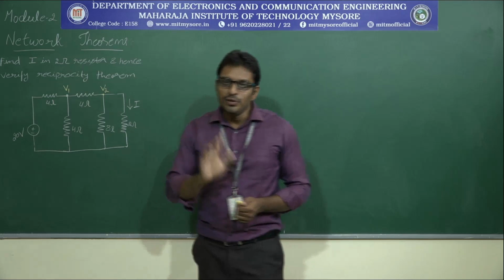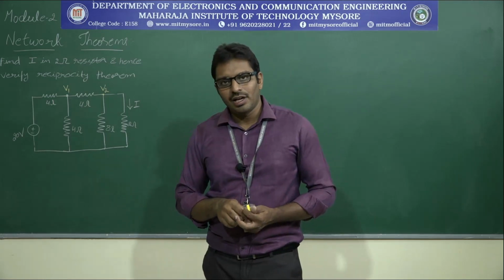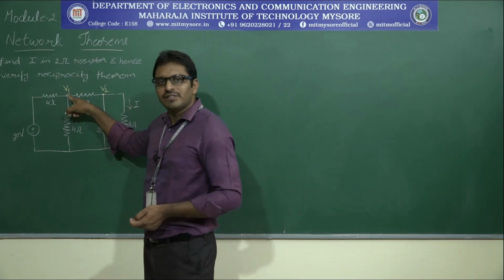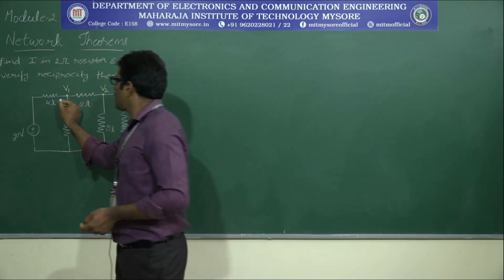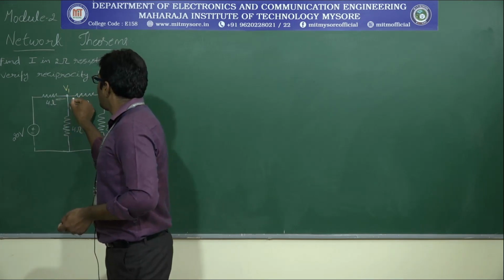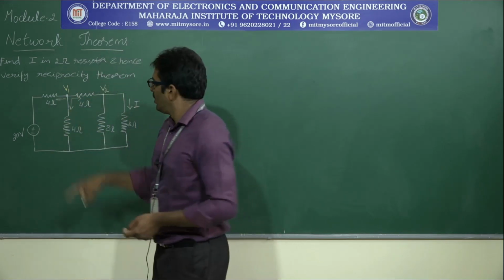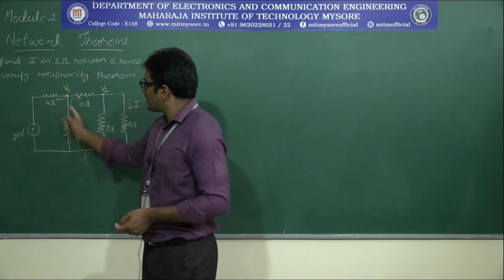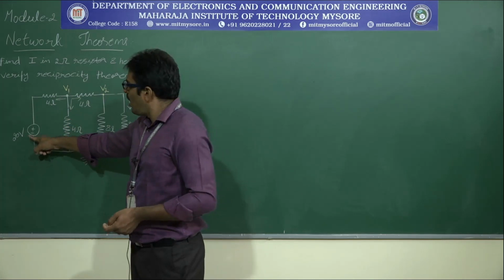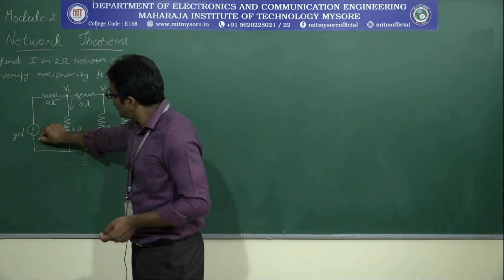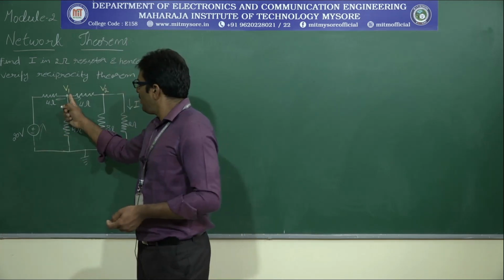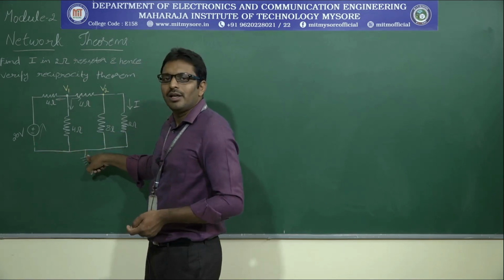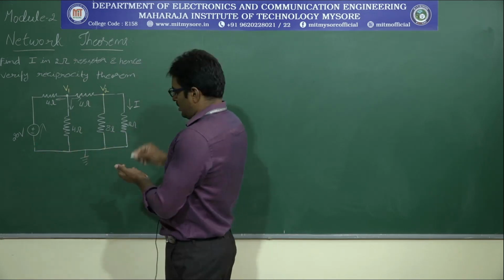All of you already know how to apply KCL for any circuit, I mean any node. When you are applying KCL for this V1, just consider this is a higher potential node, therefore all the branch currents are leaving from the node. V1 to ground, another terminal is connected to ground. At the same time, one more voltage source is there. According to this voltage source polarity, it drives the current upwards. That's why V1 minus 20, after that where it is connected, ground point, minus 0.